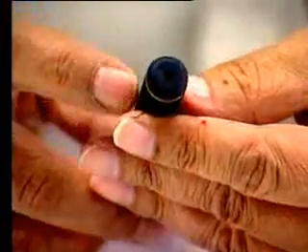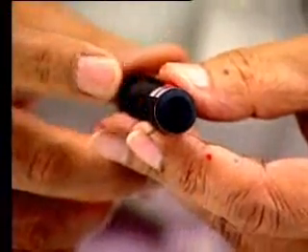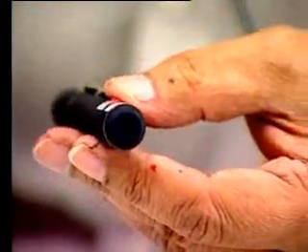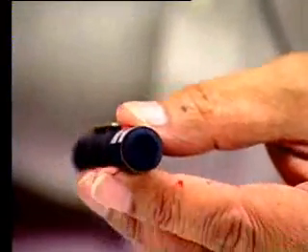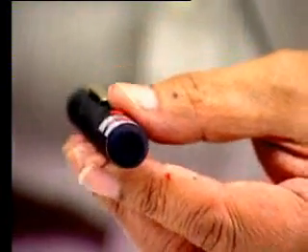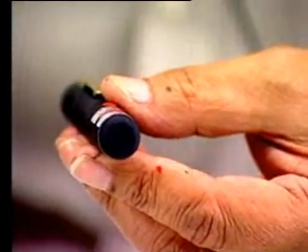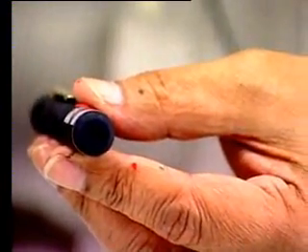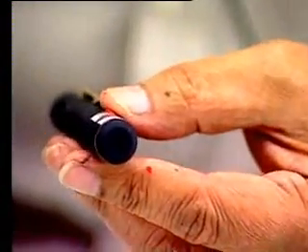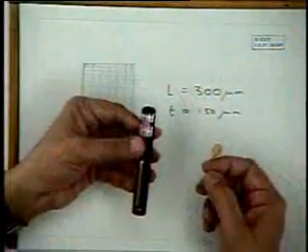This is a visible light emitting device. The output power, it says, is about a few milliwatts. So it's reasonable, of course. And of course, this is watts of power. So that's the basic difference. But this can only be worked under pulsed operation, 200 nanoseconds, because the duty cycle has to be very low, because the overall power depends upon the current times voltage times duty cycle. And the duty cycle here should be about 1 by 1,000 or something like that. Okay, 1 by 10,000.